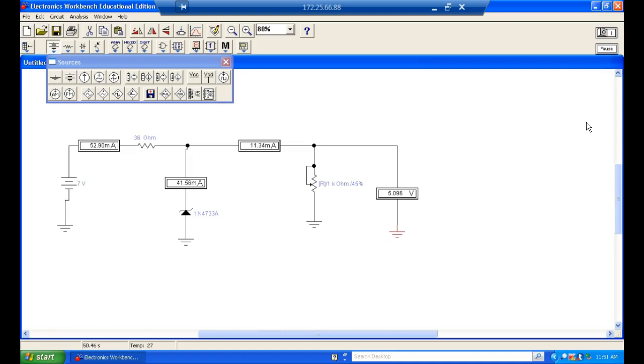That's probably going to be about the best we can do. So notice, as my Zener current goes down, to about 2.88 milliamps, I've got 10 milliamps going toward my load, and then my input current should be the sum too, right?